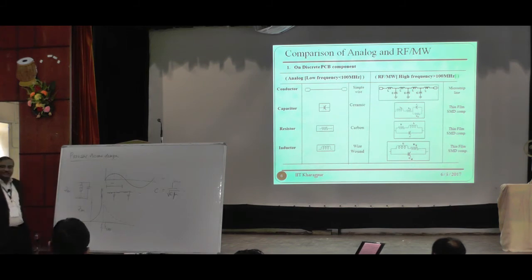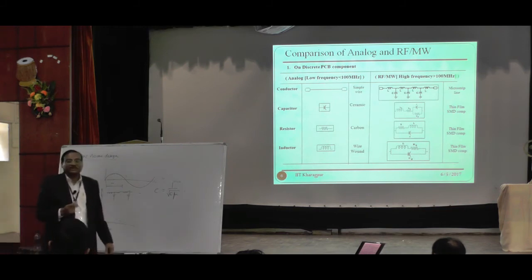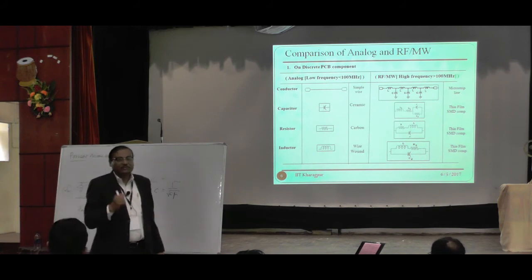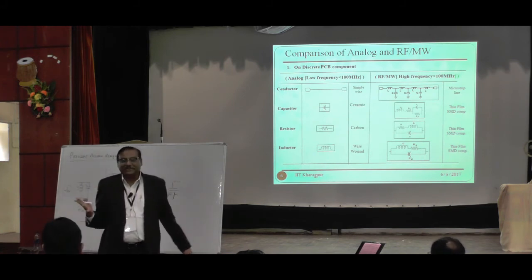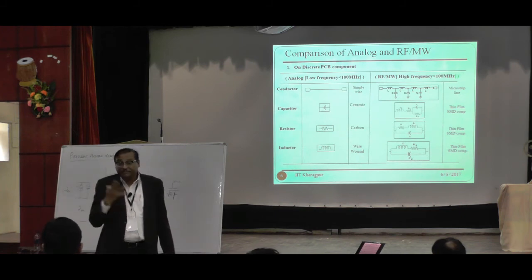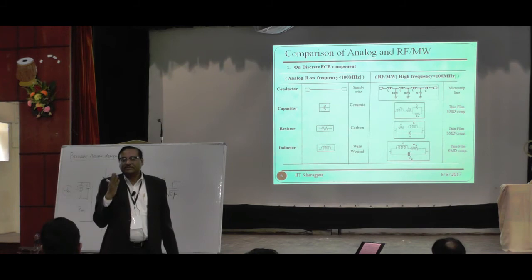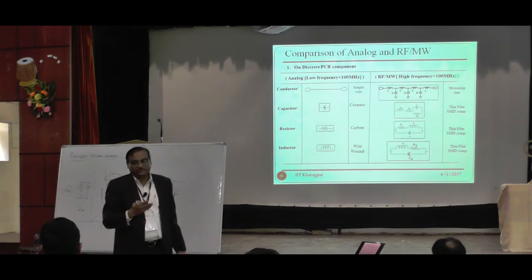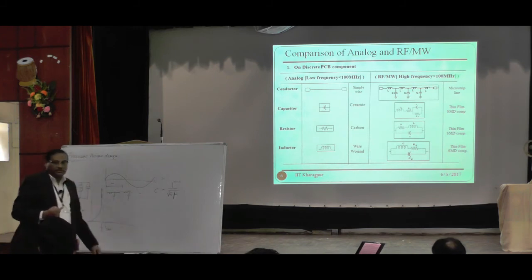So if you are designing something where the self-resonance frequency, because of this LC network, you are not aware of this capacitance, then your impedance, whatever you are thinking of as the inductive one, will basically be a capacitor. So maybe your self-resonance frequency of that inductor was 25 gigahertz and you want to work on terahertz. So the inductor will behave just as a capacitor. So that kind of confusing state will come while you design. Negative values will come. And you have to be aware of those parasitic effects. Okay? How do you resolve this issue?